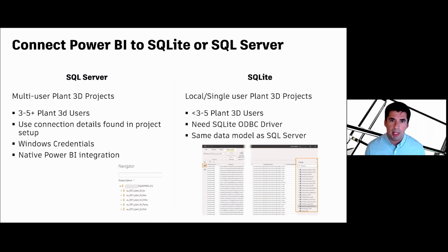When you're using Power BI with Plant 3D, you'll have to install the SQLite ODBC driver. The instructions and steps for this are all captured in the handout for the class. The data model for both scenarios is the same between SQLite and SQL Server, so all of the techniques demonstrated here will apply to both situations.